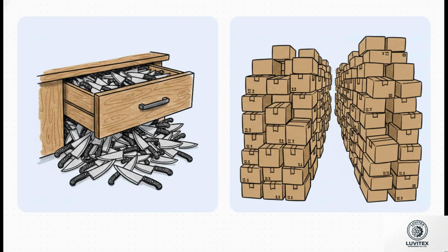Next up is I for inventory. And man, this brilliantly illustrates how excess hides underlying problems. At home, hoarding 15 steak knives when you only ever use 4 just makes that pile on the counter larger and way harder to dig through. In a manufacturing setting, excess inventory means hoarding raw materials or having a massive backlog of work-in-progress products. And the impact? Well, it ties up your company's cash, it eats up incredibly valuable physical floor space, and worst of all, it masks production issues because you always have extra lying around to fall back on.